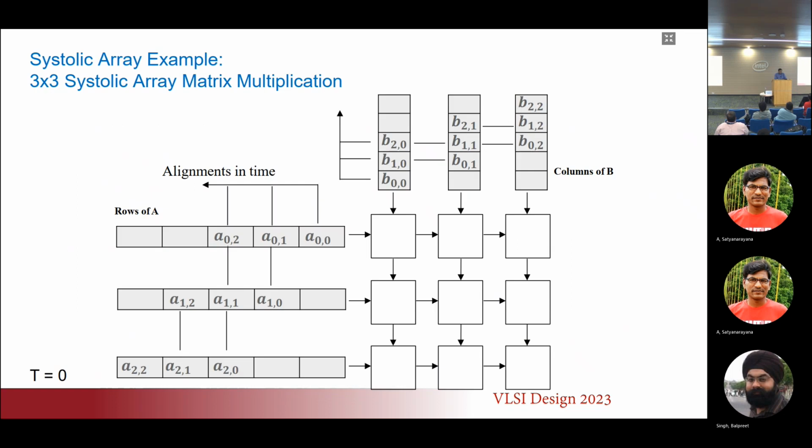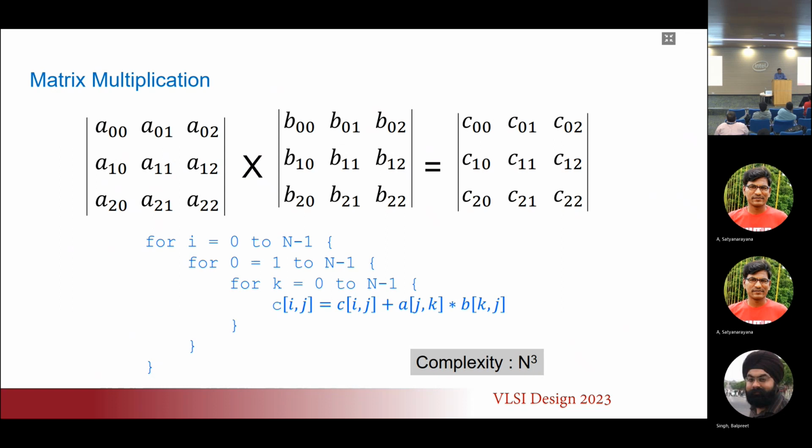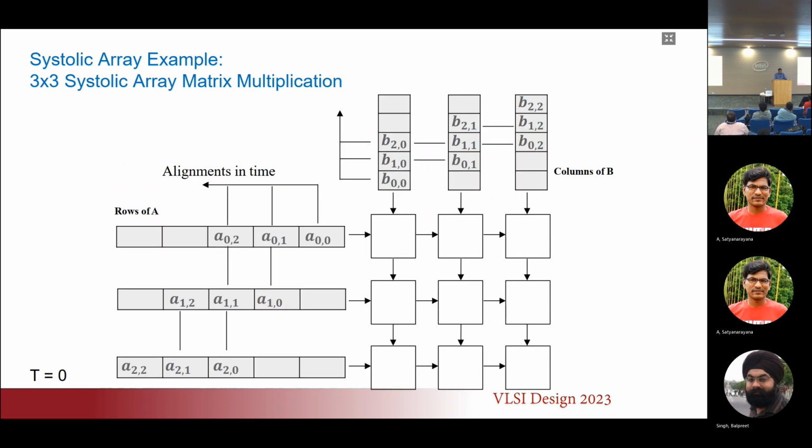And let's look at how a systolic array is going to function. I take the same matrix A, B, etc., and I have registers, and I put those values in these registers. These are shift registers. The value A00 is sitting in this register, A01 sits here, A02 sits here, A10, A11, A12, and as you can see, they're all displaced by one position in this alignment.